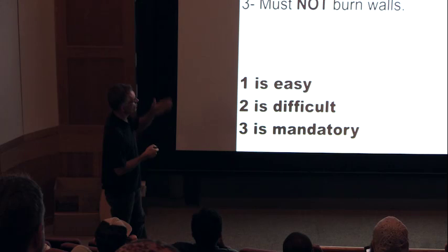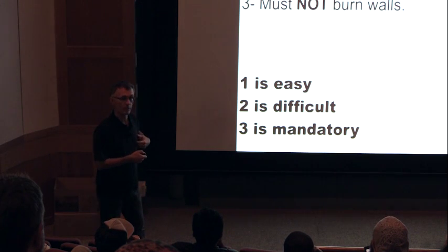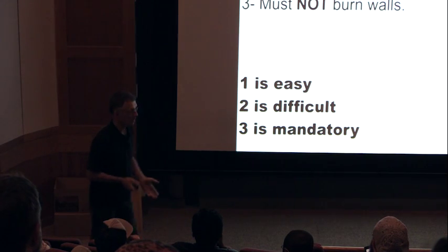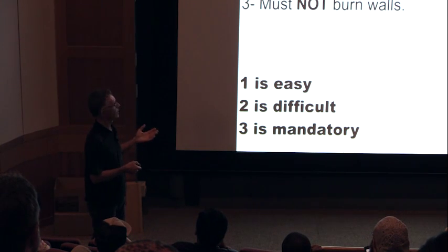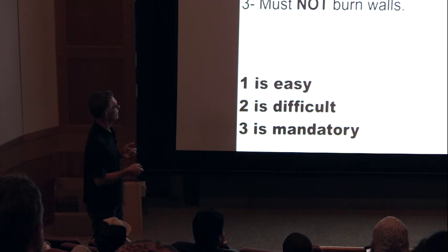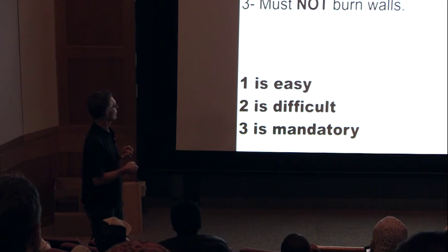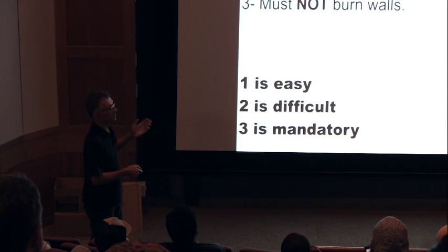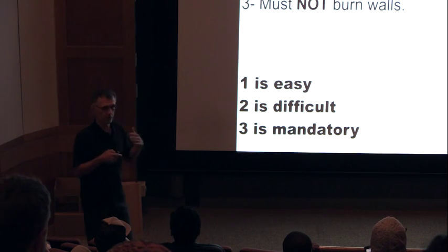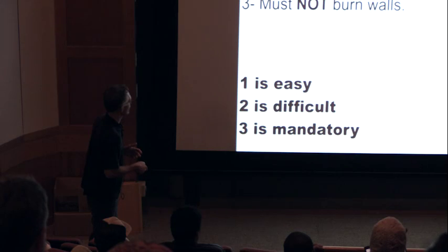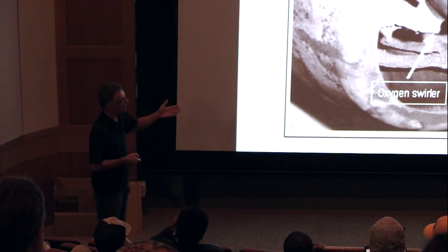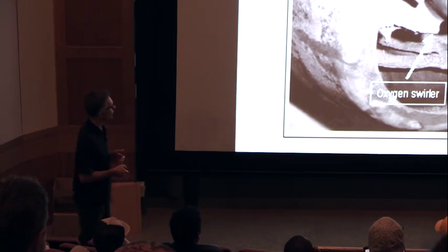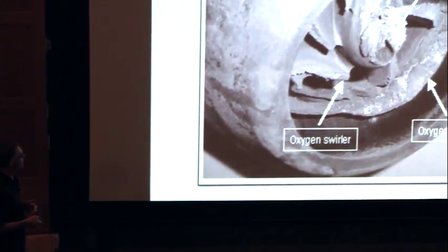So that means if the pressure goes up at the inlet, we must control the pollutant emission. And the most important thing is that when the pressure goes up, all the temperatures go up, and the walls may die. And that's, of course, not negotiable. Okay? So doing 1 is easy. We always burn almost everything. Doing 2 is not so easy, but doing 3, you cannot just say, I'm doing well here, okay? You have to do that. There's just no way. The engines must survive. If it does not, you get these pictures which I've shown before. Of course, then the show must stop there.